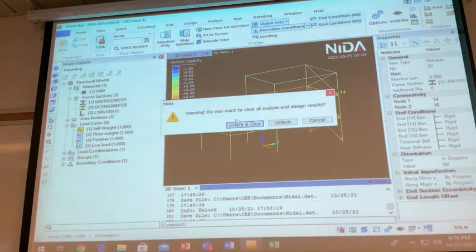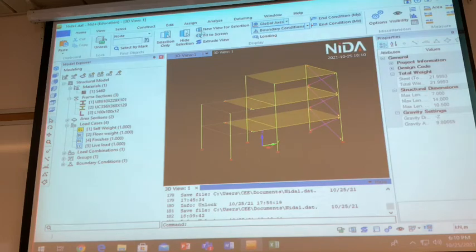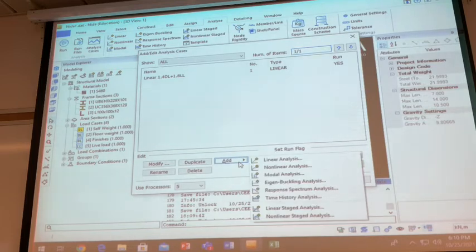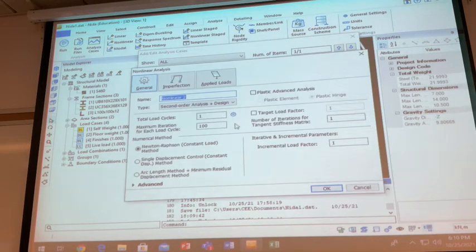So how to use the second order or linear analysis? Now, this is a linear analysis. Linear analysis is just for you to get the loading and then design based on the linear loading distribution. But now, second order analysis can help you to design for the buckling effect or geometric nonlinear effect. You don't need any calculation for the buckling effect. Okay, so this is very convenient. When I want to design by second order analysis or nonlinear analysis, I should go to the app and then nonlinear.